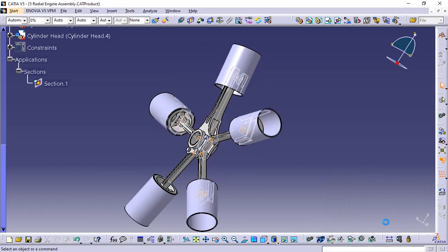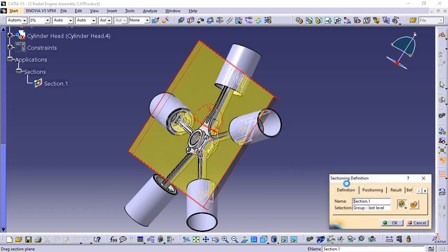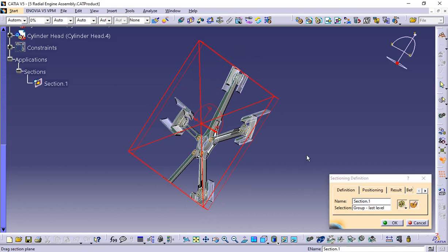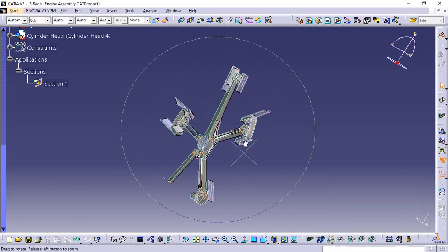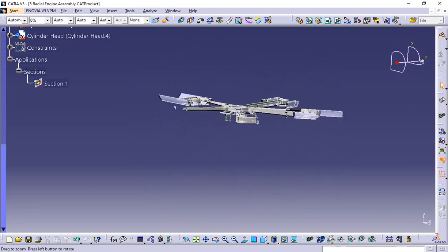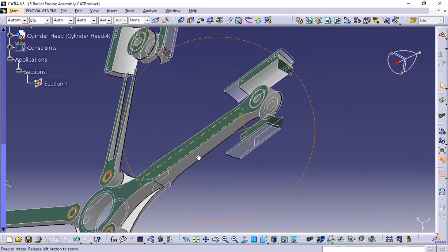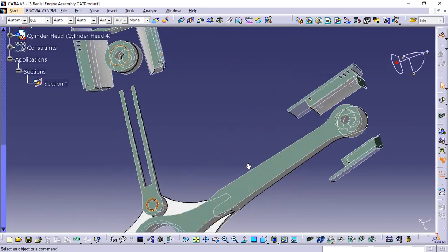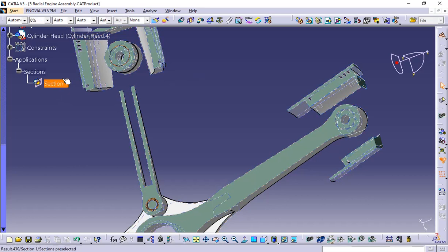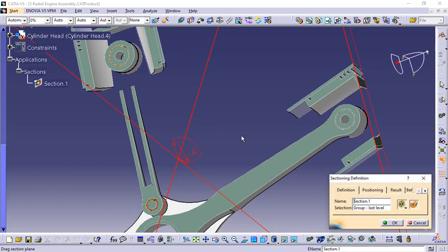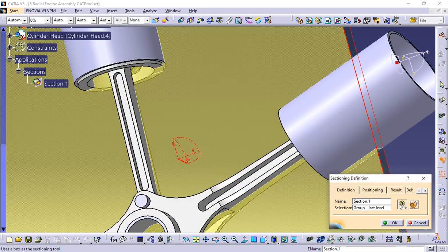If you click OK, you just click on this volume cut, clicking OK. So you can see the box volume cut in all the different directions here. So these are some of the options that based on the requirement we can use, whichever section you want, and you can see by selecting this volume cut in the assembly design workbench.